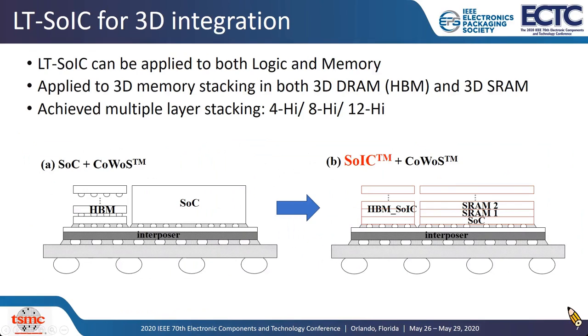After the review on the strong foundation of SOIC technology, here I would like to introduce our newly developed low-temperature SOIC technology for 3D integration. We focus on its potential application to multi-layer memory stacking, including 3D DRAM and 3D SRAM, which we have achieved 4-high, 8-high, and 12-high stacking.